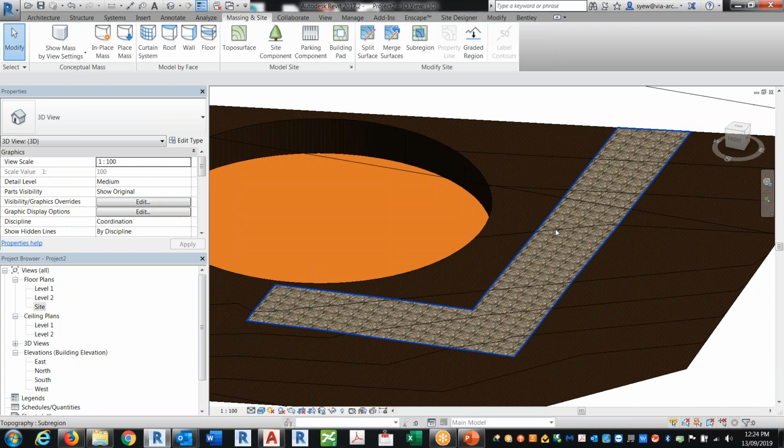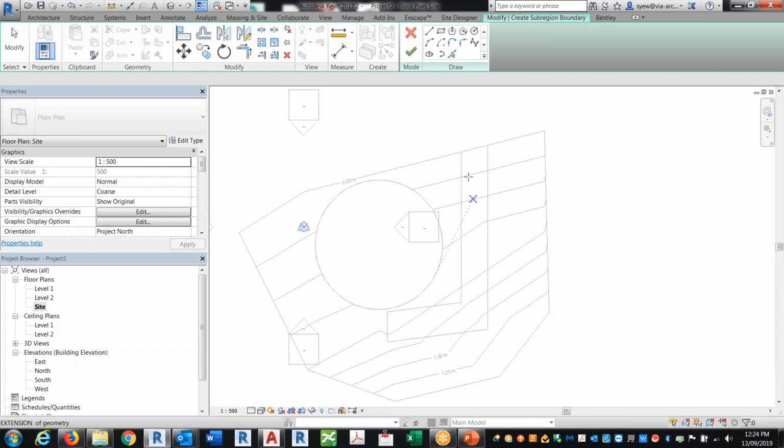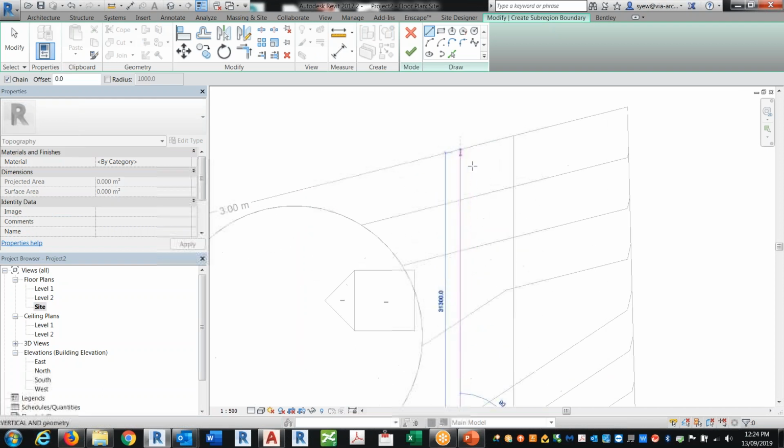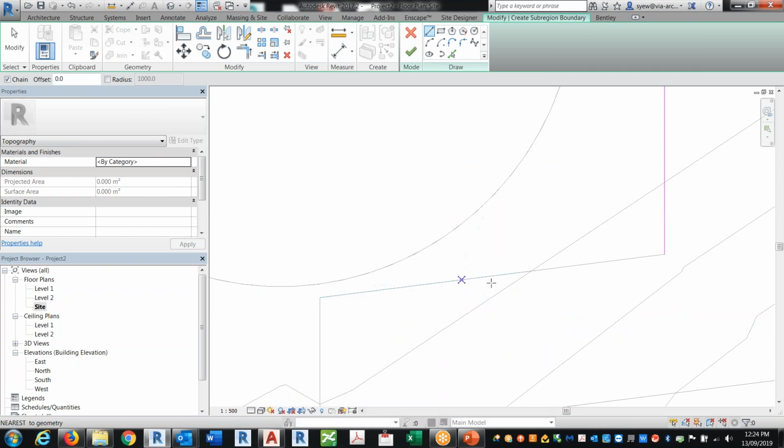That's correct. Yes. Now, keep in mind, you will run into this problem where you have to create a side road. Let's say, for example, you want to do a road, but the problem is that none of this line will snap, unless you do an edge. When you're doing topography, you can snap onto the region of the road, but you cannot snap onto any of this particular. Let's say you want to do this edge, you can only pick end to end.